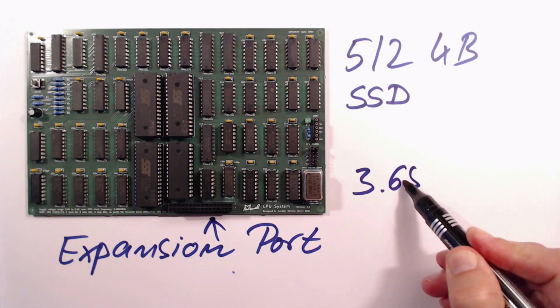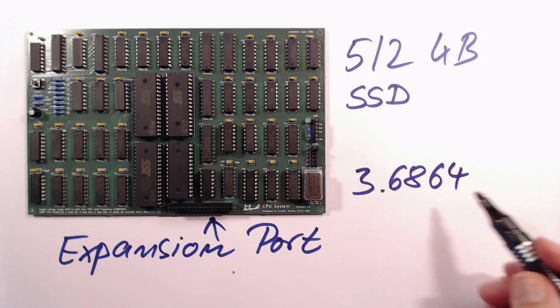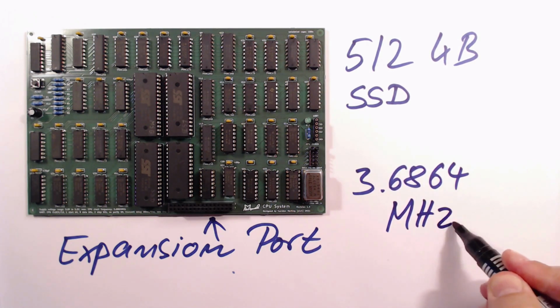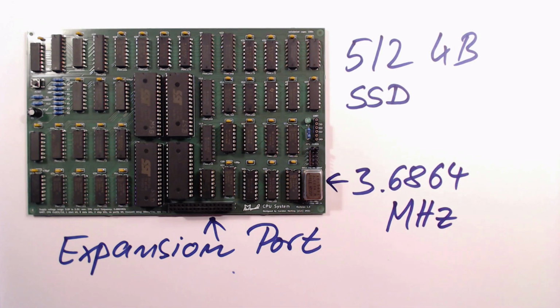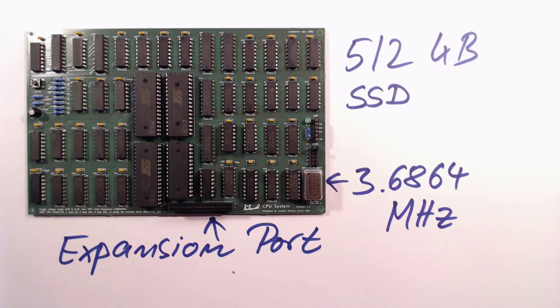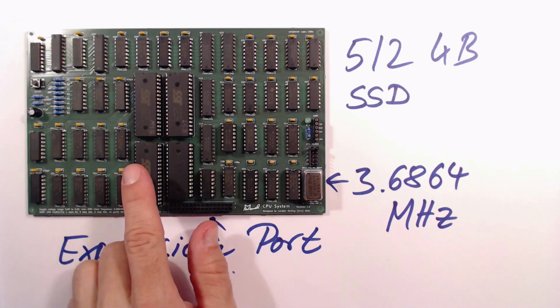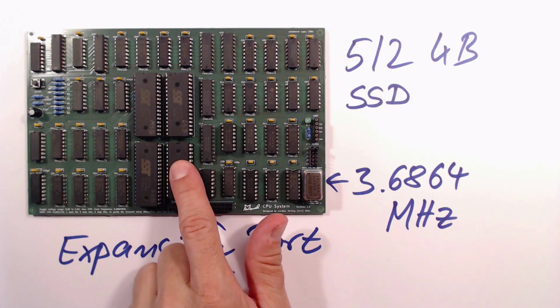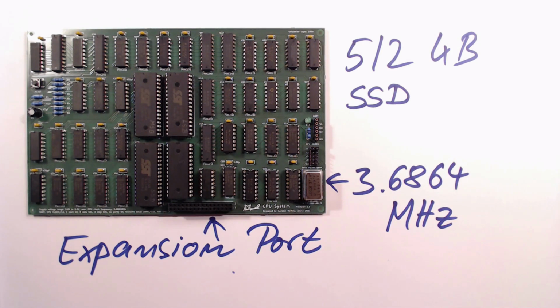DIY CPUs usually have a quite limited address space shared by RAM and ROM. My CPU, for example, features a 16-bit address register reaching 64 kilobytes of memory. I'm using 32K of flash and 32K of RAM. For a larger address space, the number of connections quickly explodes, usually enforcing higher circuit integration, which contradicts the point of a minimalistic CPU design, so there's a kind of sweet spot here.